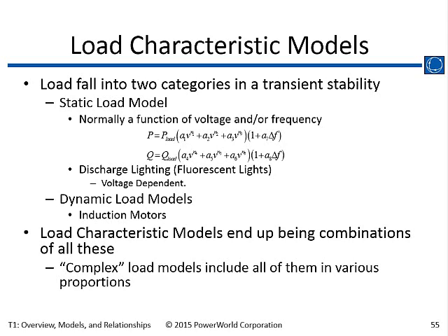There's not a lot, and we can address them because we'll see all the generators settling down, and then one goes like that. And you just look at that model and figure out what's going on with it. Like there were some models that had negative droop in them, which is not a good response.